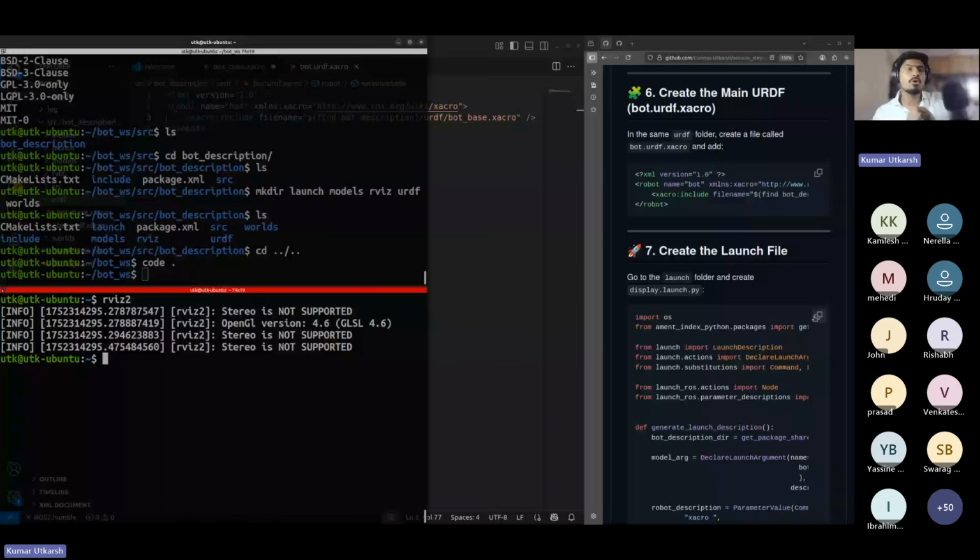You can write a node for motors that subscribes to the command velocity and commands the motors. The nodes communicate with each other in ROS via something known as topics. One node publishes to a topic and the other node subscribes from that same topic.